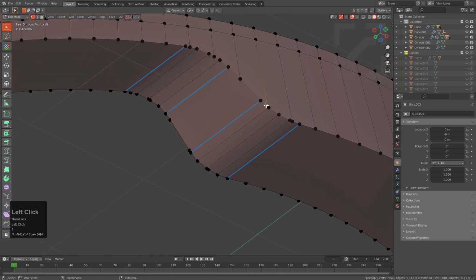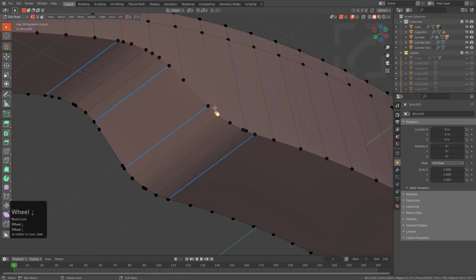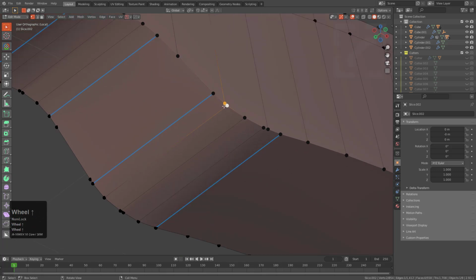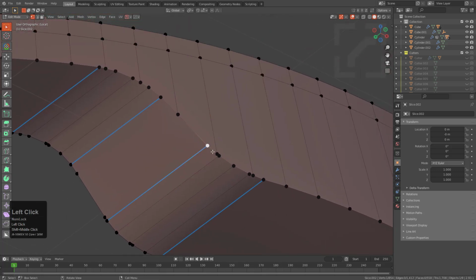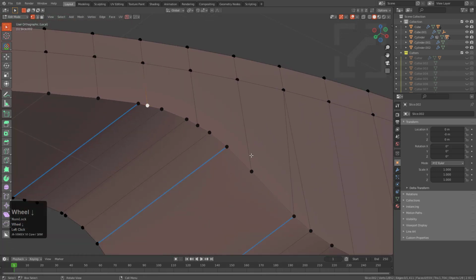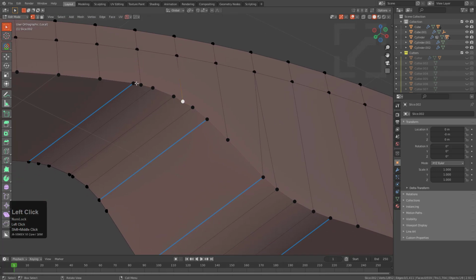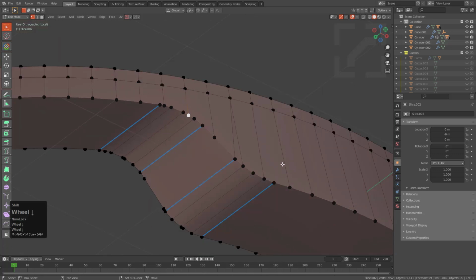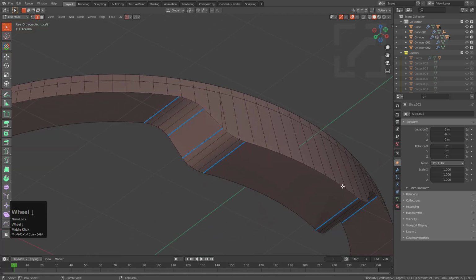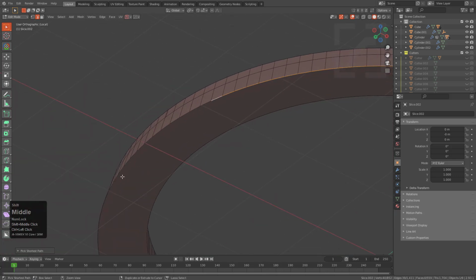However, we want to look at the geometry and make sure there's not any super near misses, and there are. So it's, do we want to sacrifice topological integrity in order to get rid of these near misses? I guess so. Sometimes in these cases I experiment with different strategies for dealing with geometry, but in this case we'll settle for these near misses. But for this one, we'll hand this one off to a different vertex just to ensure that nothing happens with the topology. We'll select this edge and control click to this edge.